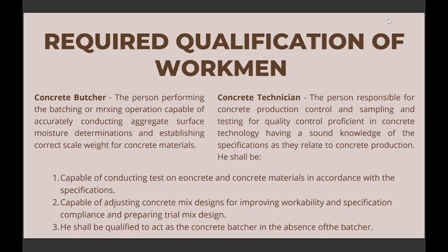Required qualifications of workmen. Concrete batchers. The person performing the batching or mixing operations must be capable of accurately conducting aggregate surface moisture determinations and establishing correct scale weight for concrete materials.